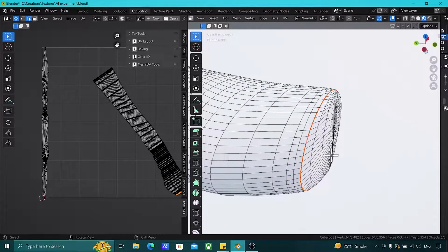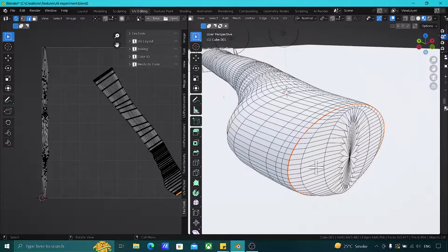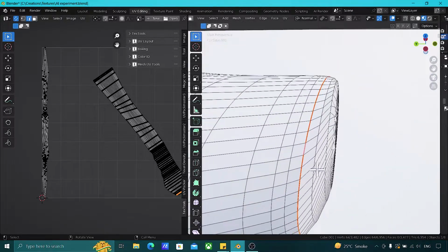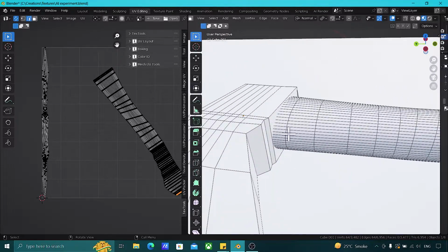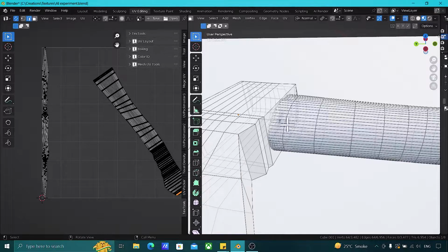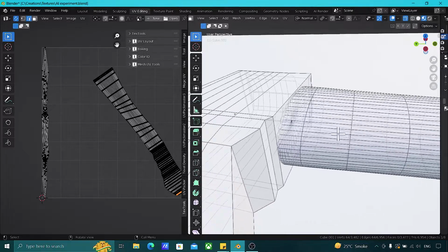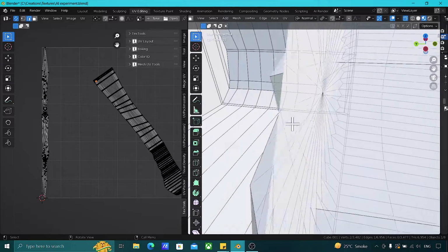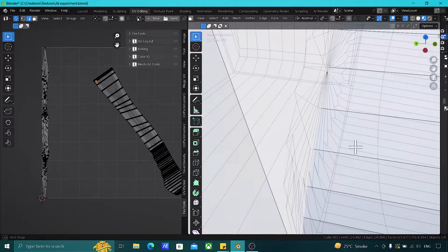As I told you in the earlier video, the seams break the 2D texture according to the 3D model on the surface. All right. So this is the seam that we are going to use in here, and then we need to go to the top. You need to go to the X-ray view by pressing Alt Z and see if there is an edge that we can use as a seam, so that it will be hidden also, and we can get our proper seam and flow of the texture.